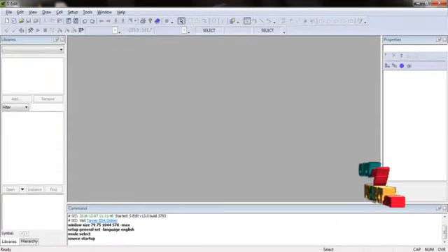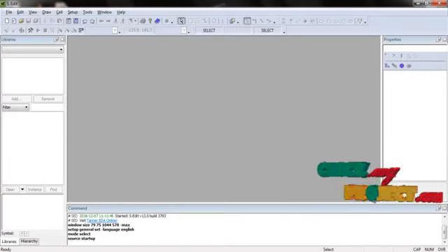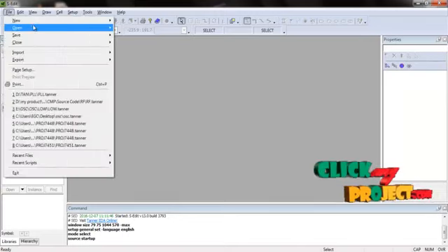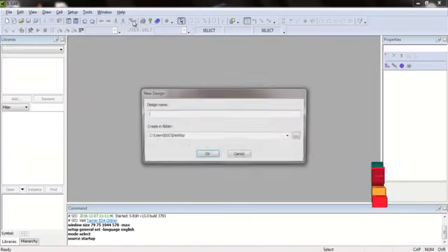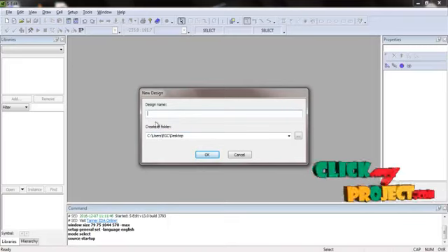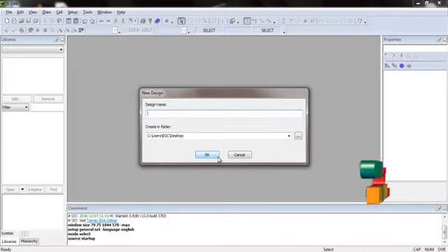Now we are going to discuss about the running procedure of our product. Our product can be implemented by using a Tanner EDA 13.0 version tool. First, create a new schematic using this file menu. File to create a new design. Assign the design name on the desired path. After assigning the design name, click OK to continue our product design.